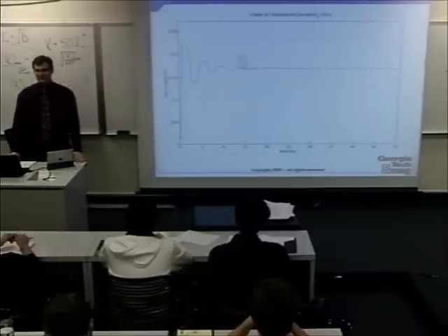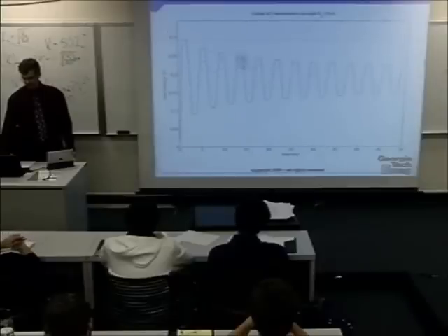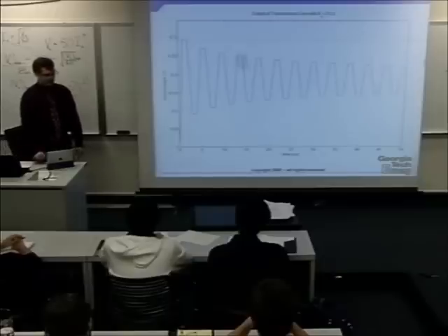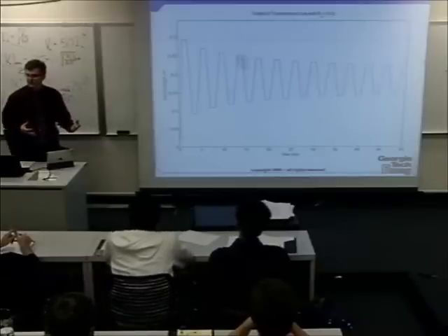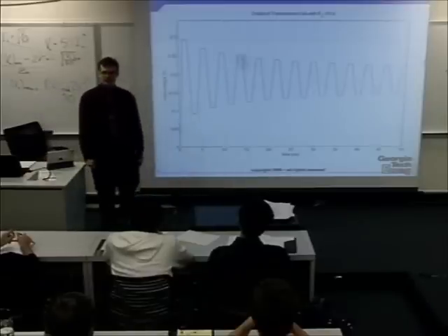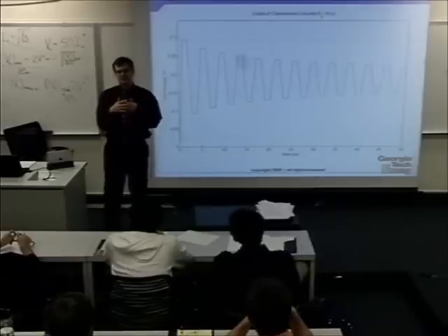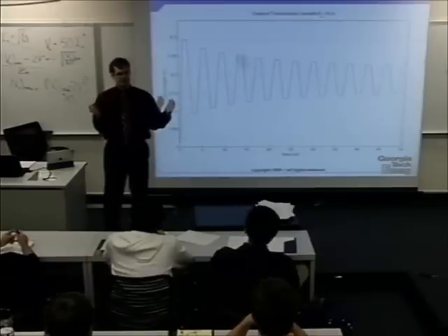Well, let me show you. This is kind of interesting. Let me show you what happens when you drop this to 10 ohms. Well, this is very typical of nonlinear circuits. This is one of the reasons why many of our instructors, including myself, are scared to teach nonlinear circuits, because they do weird things. In fact, I've been telling you these DC charging problems, and I always say, oh, what happens when this is connected to a DC source for a long time? Well, here's an example of a nonlinear circuit that never reaches a steady state.